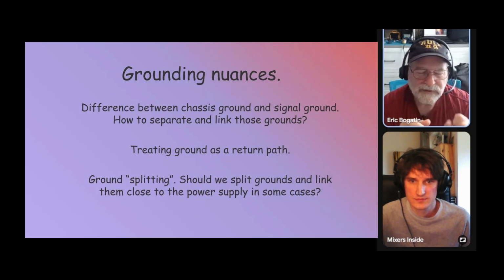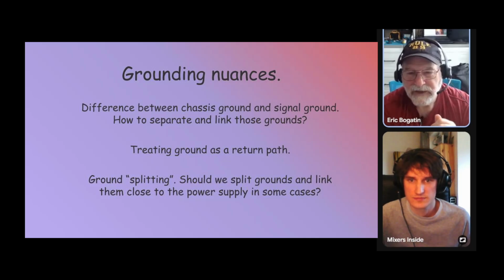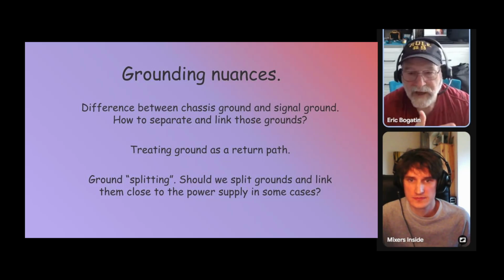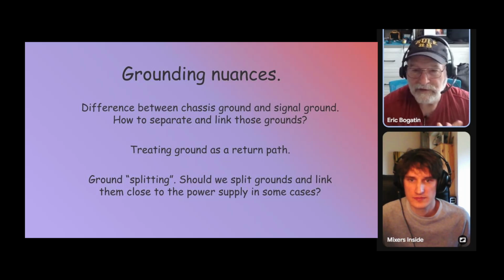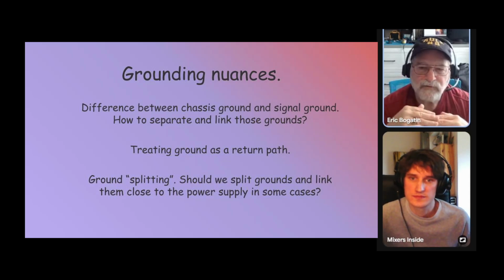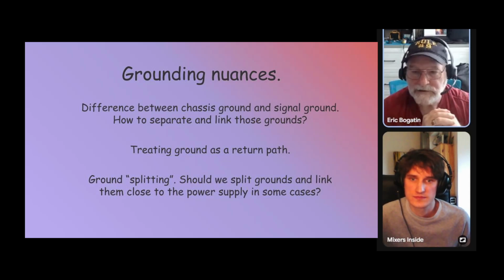In most instruments, chassis ground inside the instrument, when you plug the power cable inside the box, the earth ground is connected to chassis ground, and that is an important safety feature as well. So chassis ground is oftentimes connected to earth ground. On the circuit board, we have a node in the schematic that we call ground, which we really want to refer to as circuit ground. That is the point we're using as a reference to describe the voltage anywhere else.